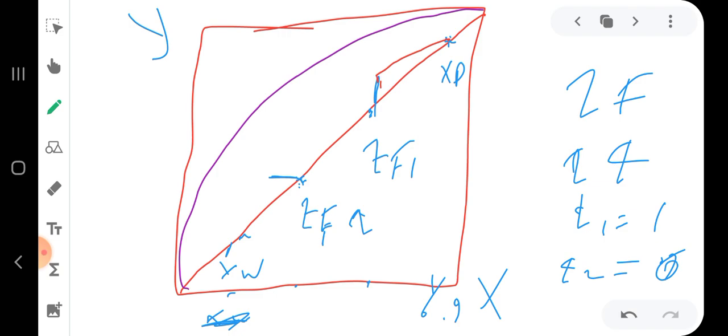Now the question here is how I can draw this line, the second operating line for the middle section. Do we have a direct equation with slope and intercept that can help us to draw this line? Actually, you can derive it, but it is going to be a waste of time. There is an easier way to draw the operating line for the second section. And what's this way? This way is to use the slope value.